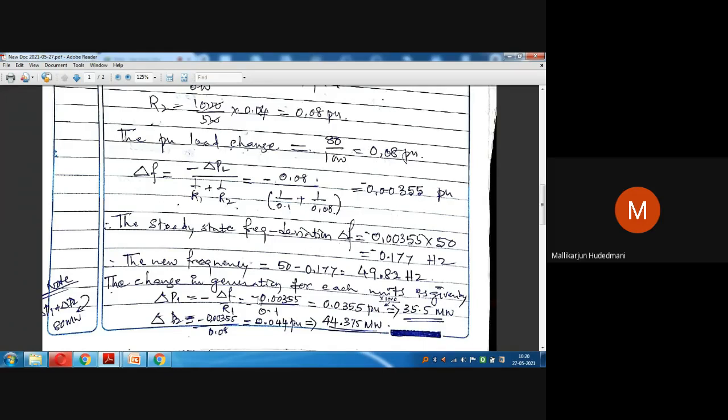This is used in the equation to see proportionate pickup by the generator as a droop relation. So this is how interestingly it is connected. Delta F is reflecting the load in terms of frequency. That drop is reflected with the droop by the value delta P in machine 1. So this is how it is connected to delta F by R1.